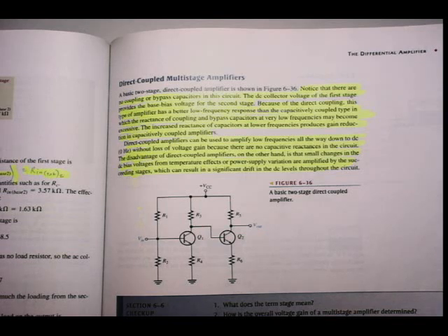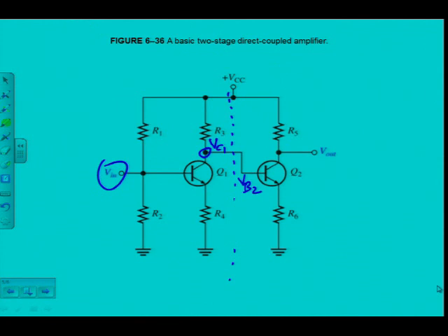Remember now, say there are outside influences that vary this voltage on the output here, then this voltage is also going to vary because of temperature and whatever. So I may get a drift in later stages as I carry on because of these voltages that may vary, because I'm using the output voltage of the one stage to drive the input of the second stage. Previously it was blocked, and then I had another voltage divider, for instance. Alright, so that's the disadvantage of this amplifier.